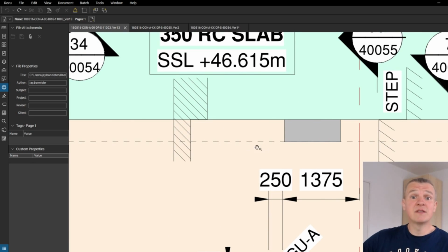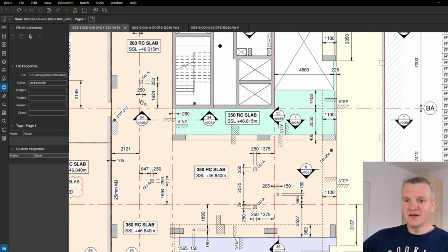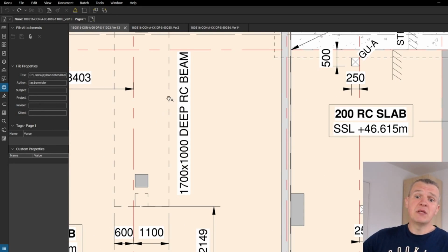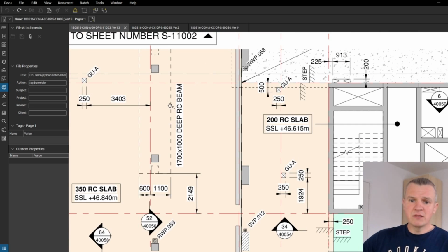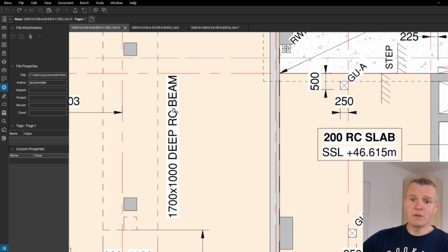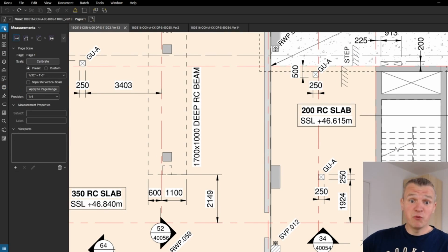So actually a step in the software is a dash line. So that's the thing. Once there's a dash line here on site, you don't really need these markups. But let's say the designer tried to really help us, and he made a lot of stuff here. But we're going to come back to the beam, for instance, because let's be honest, there will be a step in the soffit as well for the beam. You could obviously say it's not a step in the soffit of the slab, but there will be a step. So there will be a step created for the beam, and it's not marked here, but we got a dash line. So I would really stay with the dash line, and I want you to remember that the dash line is the step in the soffit, or there's some step here. And in this case, this is an RC beam here, 1 meter RC beam. I promise I'm going to show some options here from the blue beam. So I'm going to show you the great thing here. We can actually measure here.